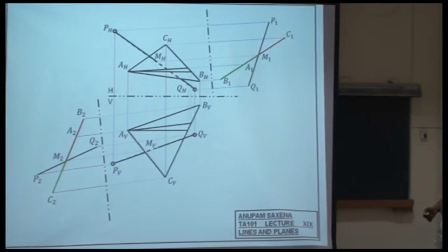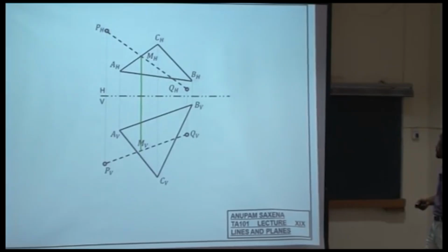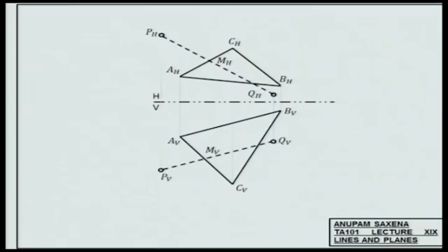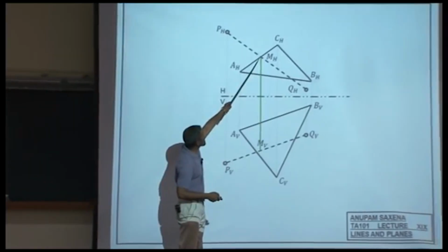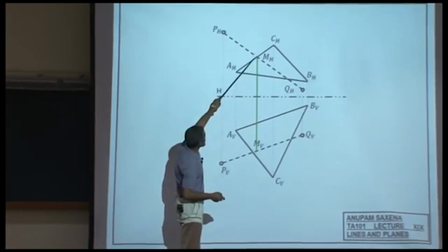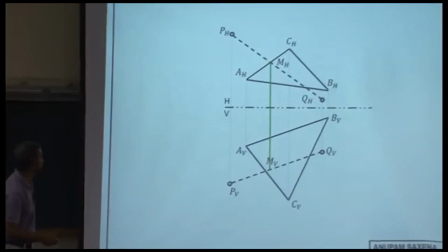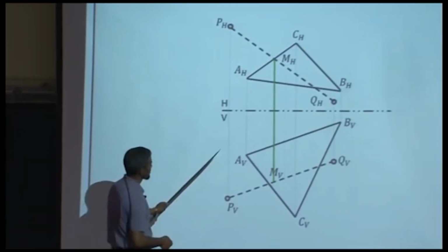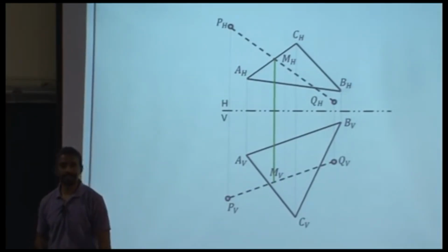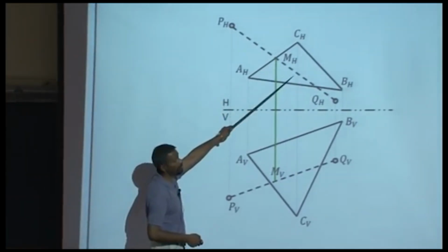Okay. Now, if I do the same thing using the cutting plane method, I hope I am doing that. No. Well, I'm doing projections. That intersection point and this intersection point, I drop a vertical from there, PQ and AC. Over here, which comes first? PQ or AC? PQ. Yeah? PQ comes first. So what part of the line will be solid there? This one or this one?